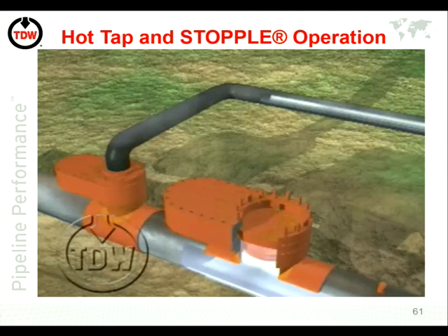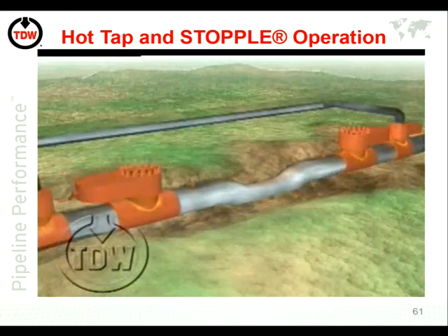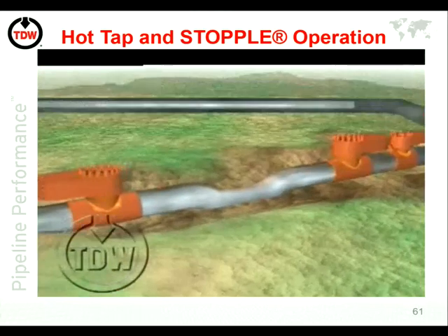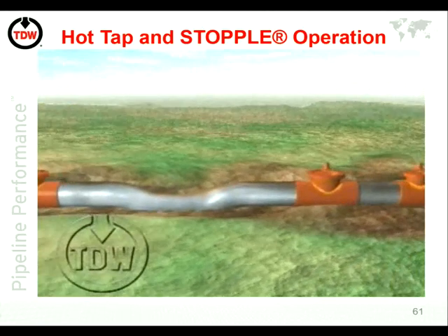So you would carry out exactly the same process on all 4 fittings, and then you'd remove the sandwich valve, and you'd put a blind flange on top of there. So, sorry, that's a jump, but that's what you're left with at the end of the operation.